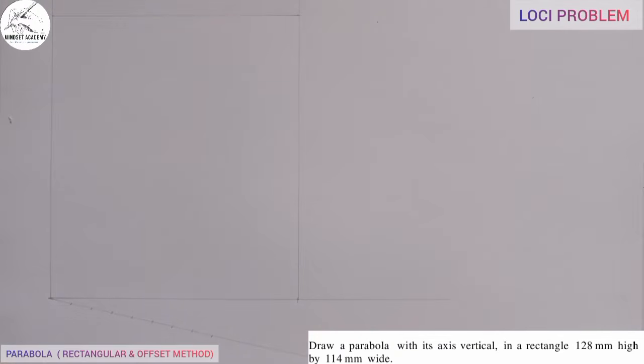Is that okay? Now the next thing I'm going to do is to connect the last point here, the 8 point, and the last point here, because I'm dividing between this line and this line. So if I call here A and here B, I want to divide AB into 8 equal parts. So I'm going to join the last point here to point B.